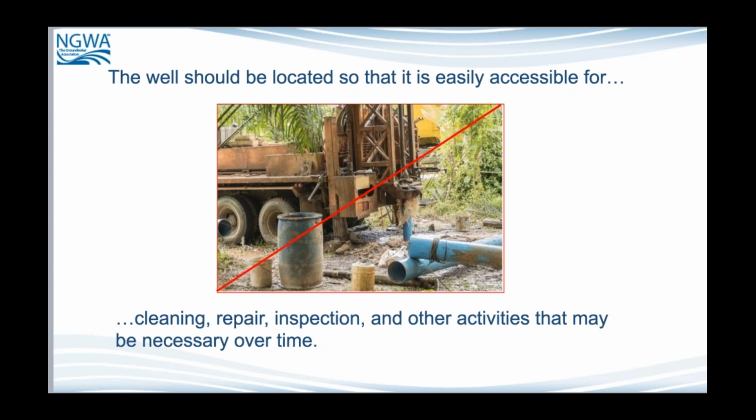Usually I like to put them somewhere near the driveway. I don't want them so close that a snowplow can come through and wipe them off, or a truck could back into them and hit them. So I want them about a vehicle length or more off that driveway. But I want them close enough that we don't have to try to get 5 or 6 or 7 truck lengths off that driveway to get to that well, where we can easily access it for working on it.